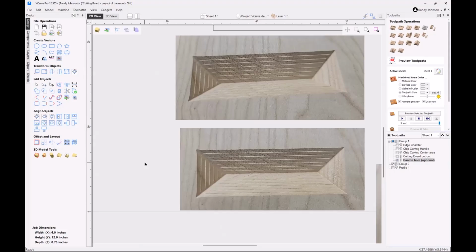There's a couple reasons for this, and tonight I'm going to focus on one main reason, which has to do with the angle of the bit. Now, just like dowels being exactly a 1/2 inch, which we know they're not, router bits are spec'd at 90 degrees, but sometimes they're not exactly 90 degrees. Now, this has become less of an issue than it was 10 or 15 or 20 years ago when I started out. Back then, V-bits were basically for putting a V-groove in a board or in the edge of a board, and nobody really cared if it was exactly 90 degrees. They just wanted a bevel.